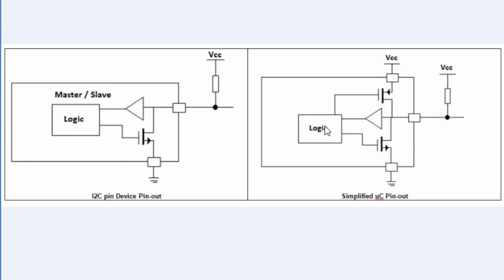That way, if we want the pin to go low, we set the pin to an output, and we have a low or a 0 in that bit for that pin loaded in the register. So as soon as you set it to an output, that pin goes low. Current flows down here through our pull-up resistor, down through the FET to ground, and we pull the pin low, giving us the low.